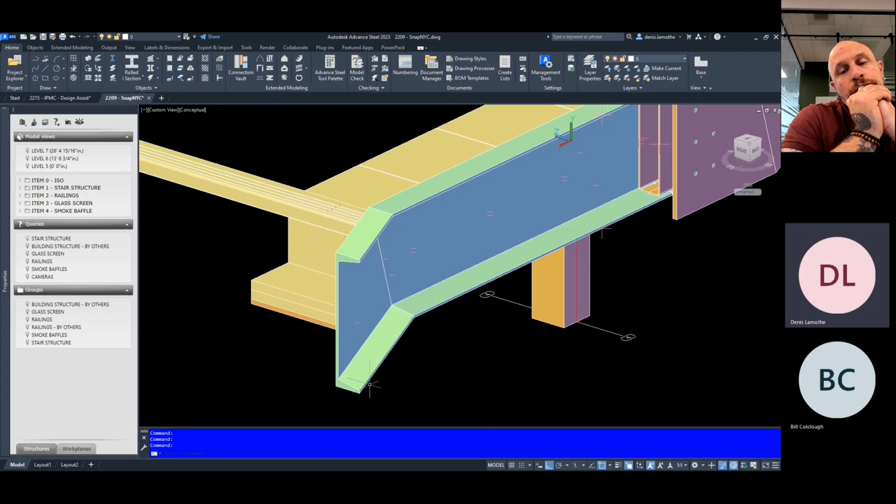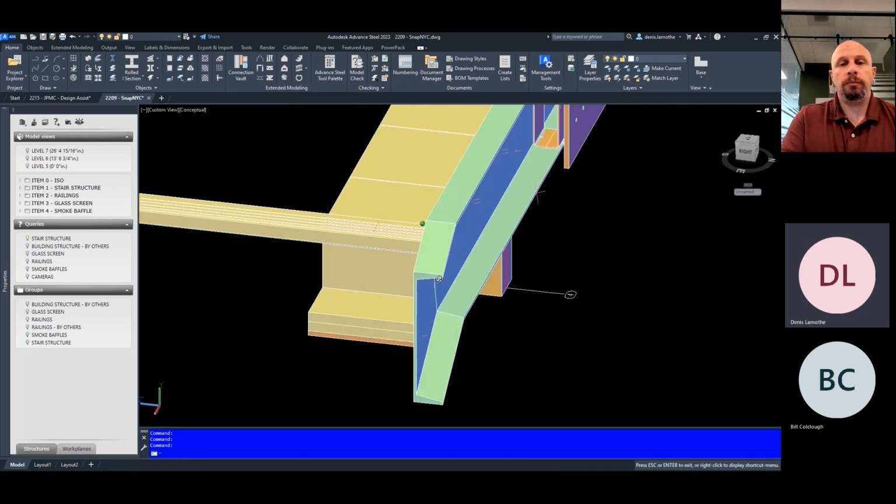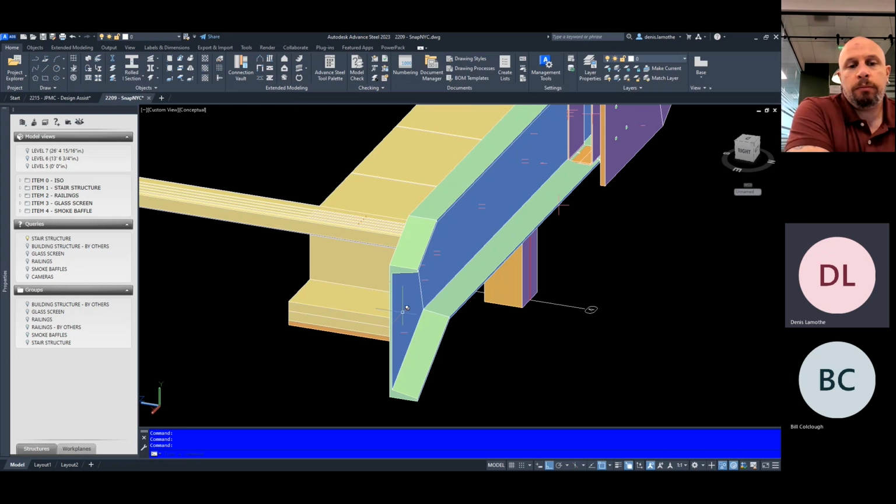And again, not generally something that architects like to see in an ornamental stair, but where there's a channel, typically that would be cladded or boxed in with some other kind of finish, whether it's wood or stainless steel cladding, painted steel maybe. And that would allow us to hide any of those unsightly little bolt heads and nuts and washers, and maybe even weld bleed-throughs when you're welding a plate through a thin web. It kind of distorts the face a little. You can see that when it's painted.